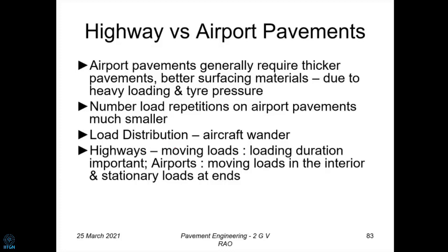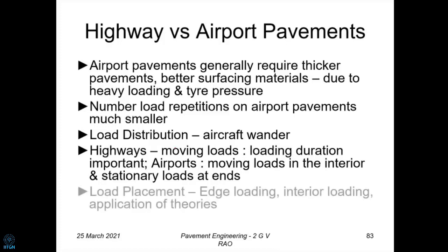So it all depends upon that. The ends of the runway are the ones which are going to be more critical, for the simple reason that the actual landing is not going to cause any damage to the runway. Why? Because it is still partially airborne. The entire load which you thought of, so many tons, is not going to land on the runway directly. It will be definitely partially airborne. That's why the turbines are still working actually. Okay, but the impact of that has to be borne obviously by the aircraft itself. That's why the aircraft structure design is going to be very important. So that is what we have to really keep in mind.